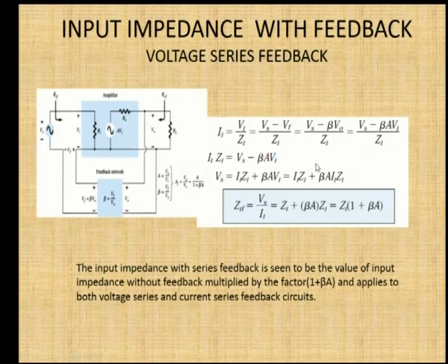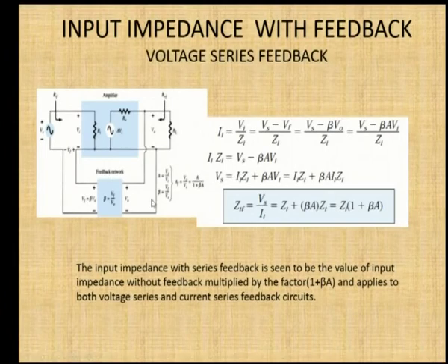Without doing this connection, you can say for this kind of feedback network, the input impedance is increased because, according to the type of the connection, voltage series. So, voltage you are taking shunt, you are connecting in series with the input signal. So, if you connect series with the input signal, what happens to the input impedance? The input impedance will definitely increase, because if the resistance is connected in series, what is the value of resistance equivalent if you connect R1 and R2 in series? So, the equivalent value of these resistors is the addition of the values of the two resistances. So, the resistance will increase.